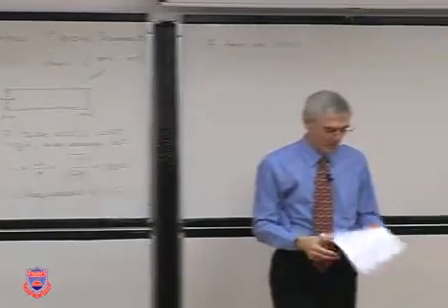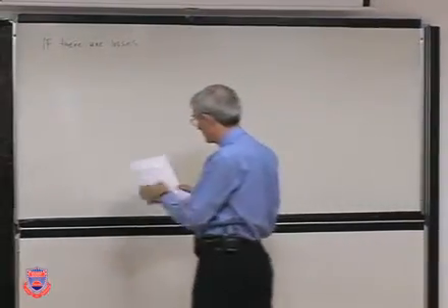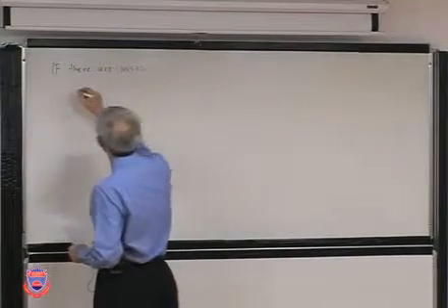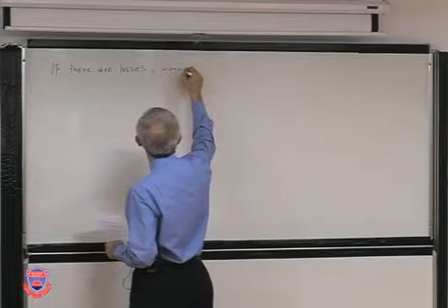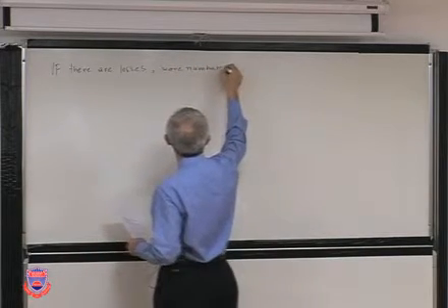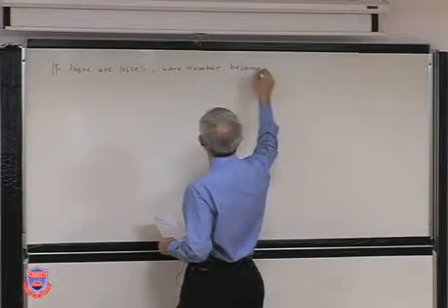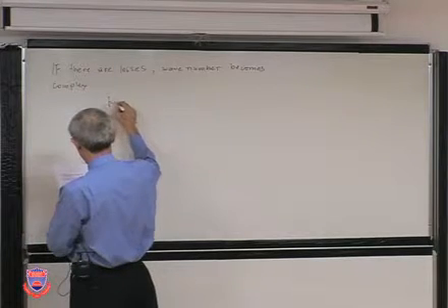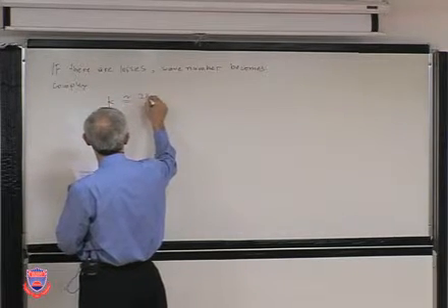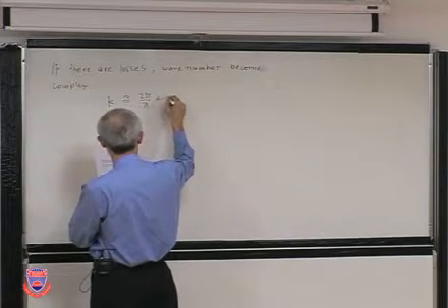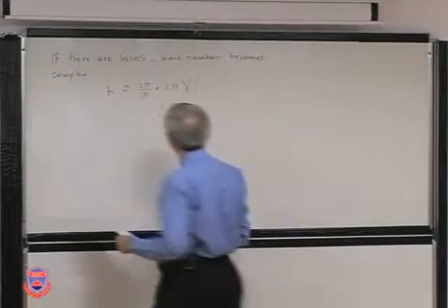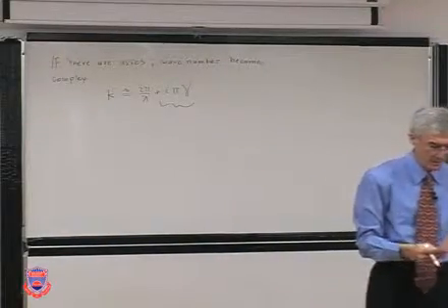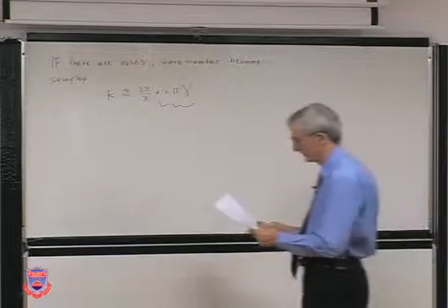So if you have liners, as sound energy is propagating, some will be absorbed. And how do you represent that? The way to represent it is wave number becomes complex. And then we represent it as 2 pi over lambda plus, and this is the additional representation that we add to it.